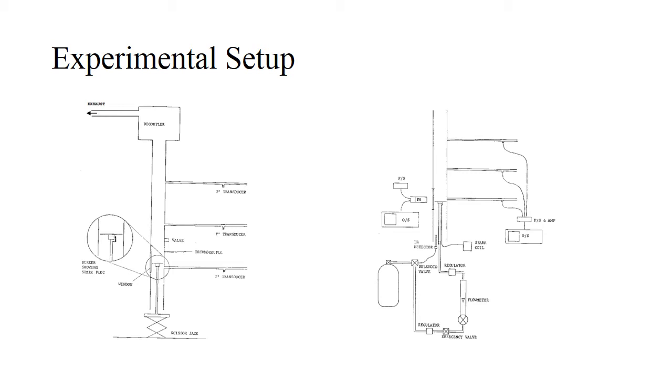We conducted the experiment by recording data from all 3 pressure sensors, the photomultiplier, at different heights along the Rijke tube, as well as the flow rate using a rotameter. We recorded data with the burner at different positions along the tube, raising and lowering it with the scissor jack. We first took data at the initial 0-inch position with the valve closed, then again with the valve opened. We then recorded data at the 2-inch station with the valve closed, and finally at the position where pulsation ceased, which in our case was at 6.15 inches.